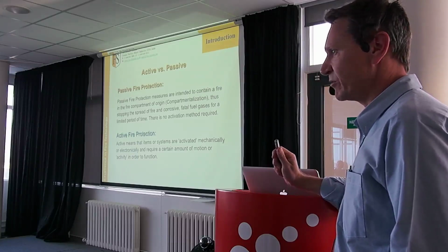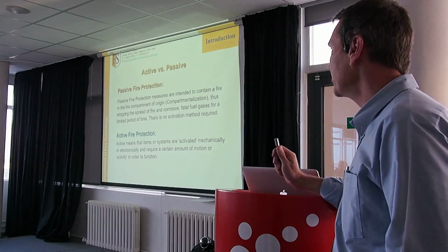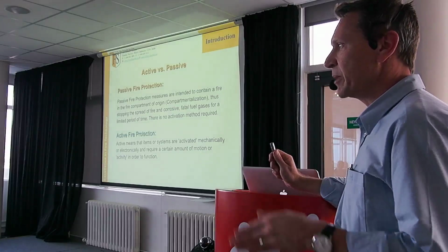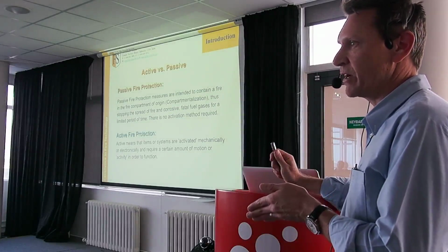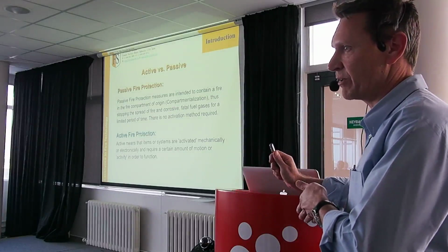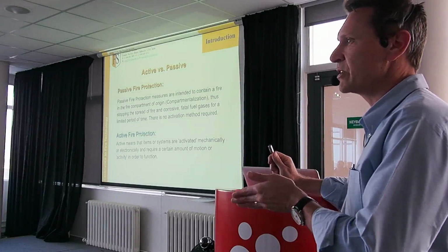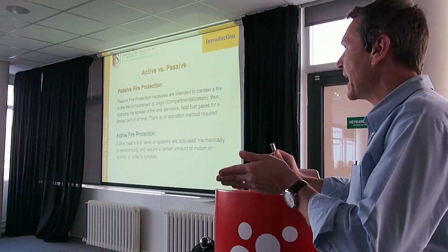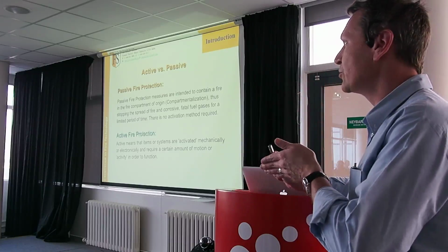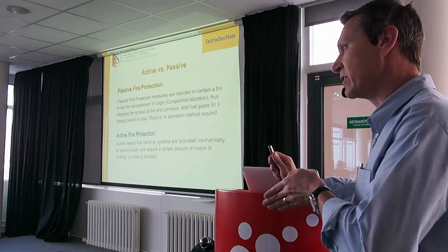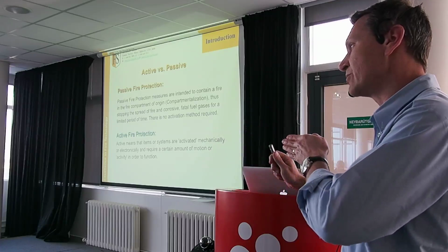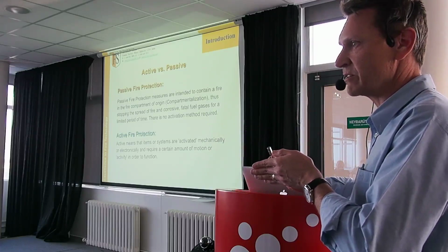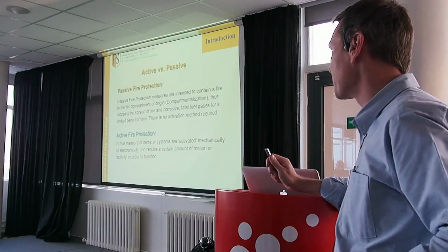It activates itself. So the limited period of time that's stated there just means that you may have a penetration seal that is 1 hour fire rated, or 2 hour, up to 6 hour fire rated. That period of time runs on its time test. On a cellulosic fire curve, at around 1092 degrees, that's a 2 hour rating. So that's how long the slow growth gets to. On a hydrocarbon fire curve, it's 1100 degrees in 45 seconds. So there's a variation in difference.